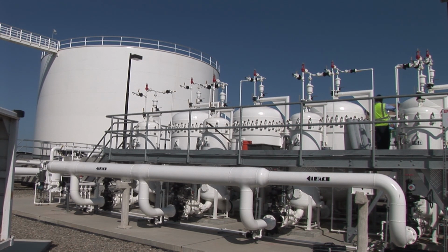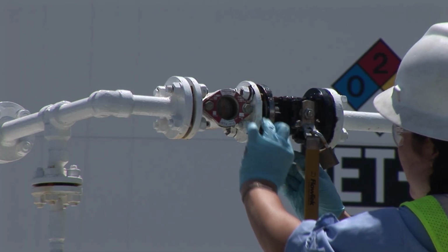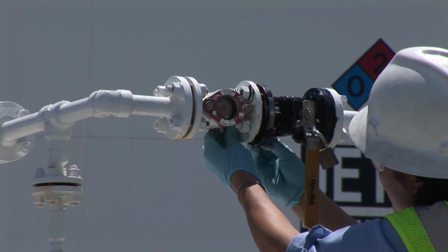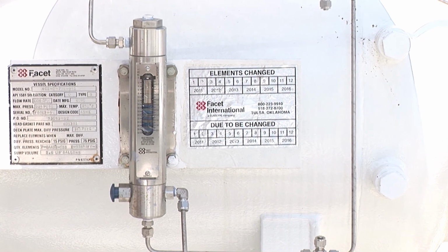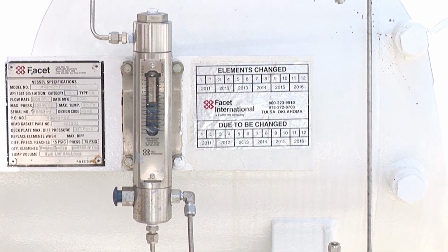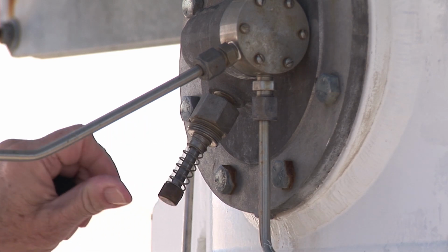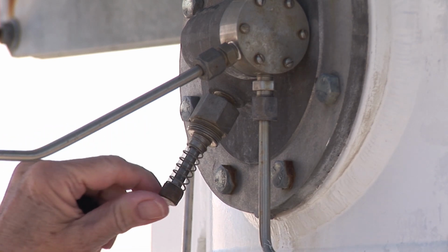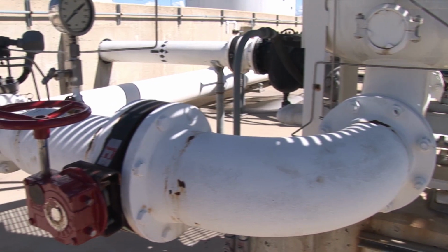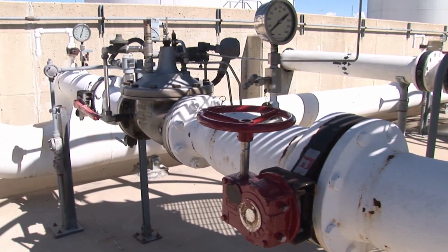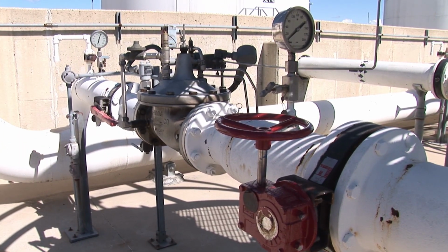The filter separator has other maintenance needs in addition to changing or cleaning the cartridge. The following items should be checked on a scheduled basis. Inspect the differential pressure gauge for restrictions and proper operation. The sump float or probe should be checked to make sure it's detecting water buildup. The water slug valve should automatically stop flow if the float signals an excess of water.